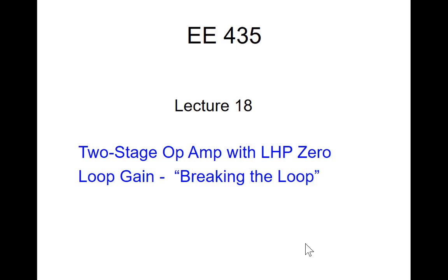Okay. So why do we use phase margin? We know a lot about what pole Q's tell us. Pole Q's tell us a lot about two important things. What do they tell us about? Particularly relevant when we're building feedback amplifiers, right? They tell us if we're going to have ringing, ringing in a step response or overshoot in a magnitude response, right? Pole Q's tell us some really important things about a feedback amplifier.